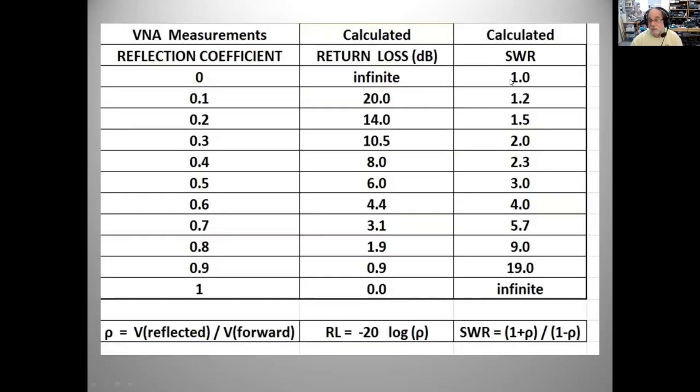If the SWR is 1, can't get better than that, the reflection coefficient is 0. All right, I know that. How about, I often get a SWR of 2 on my antennas, and my radios work fine. I can work the world. 2 SWR corresponds to a rho reflection coefficient of about 1/3. All right, wait a minute. That means I'm sending 1 volt to the antenna and 0.33 volts comes back. That sounds kind of high, doesn't it? But my antenna works fine with an SWR of 2 to 1, most of the time. How about 3 to 1?